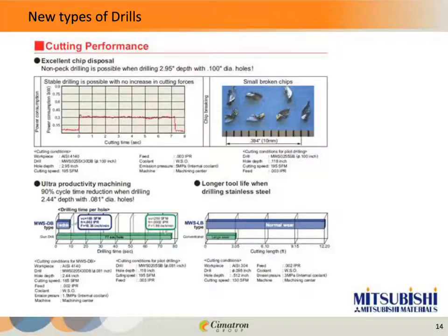Also here is the comparison of this type of drill versus a one flute gun drill. And you can see that with this carbide drill being 2 fluted, it's able to process the hole in about 8 seconds, whereas the gun drill processed the hole in 77 seconds. So it's quite a bit faster, and I wish that I had a third bar graph here to show how long that hole would take if we were using a high-speed steel drill with pecking, but I think you guys all have a good idea how much longer that would be.